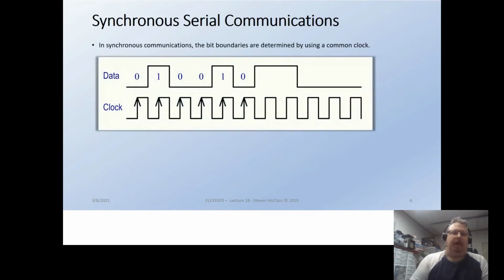on the falling edge of the clock, the data is free to change. So every falling edge, the data can change, and it can decide it's going to be a 1 or a 0 every falling clock. And then the rising clock is right in the middle, after it's had a chance to all settle down. I don't know if you've ever looked at any real waveforms, but they're never quite this square and clean. But basically, in the middle of the bit, you'll have the rising edge of the clock,